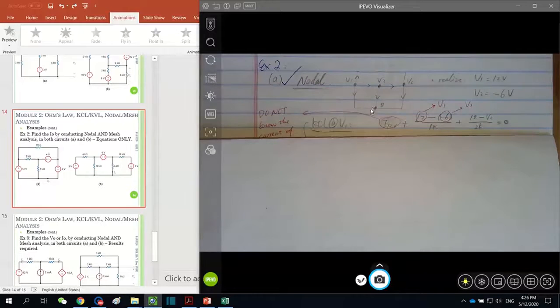To write this KCL, we need that current, and how do we get it out of the voltage source? The answer is no way. So we have to assume this current as an unknown, inevitably. By the way, we don't have a resistor connected in series with this 12 volt voltage source that we can utilize either. Therefore, we have to assume it as I sub 12 volts.